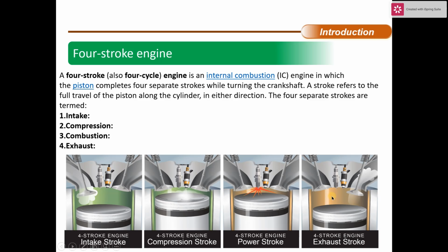Now, exhaust, also known as outlet. During the exhaust stroke, the piston once again returns from BDC to TDC, where the exhaust valve is open. This action expels the spent air-fuel mixture through the exhaust port.